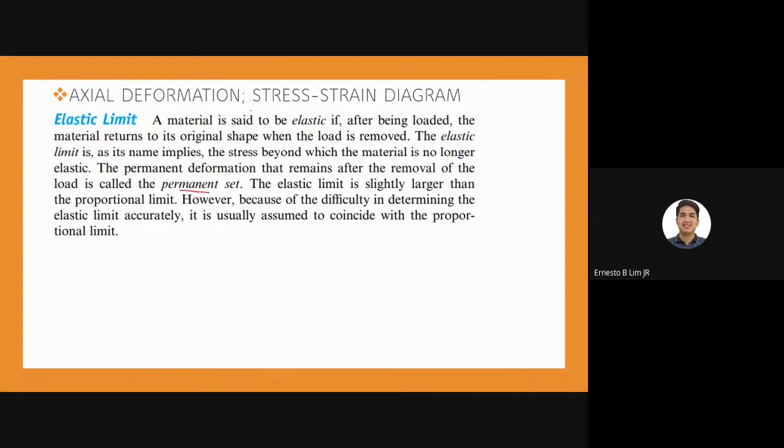The elastic limit is slightly larger than the proportional limit. However, because of the difficulty of determining the elastic limit accurately, it is usually assumed to coincide with the proportional limit. Meaning the proportional limit and elastic limit are too close in the diagram.